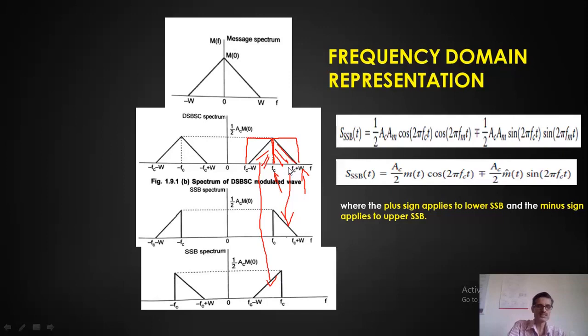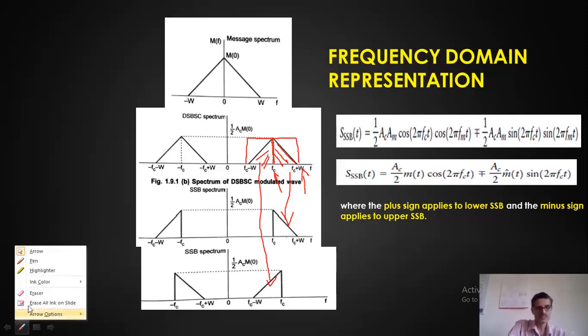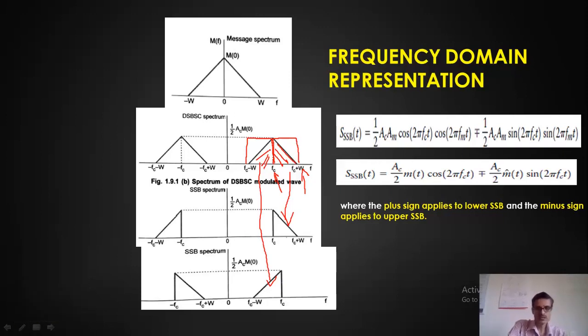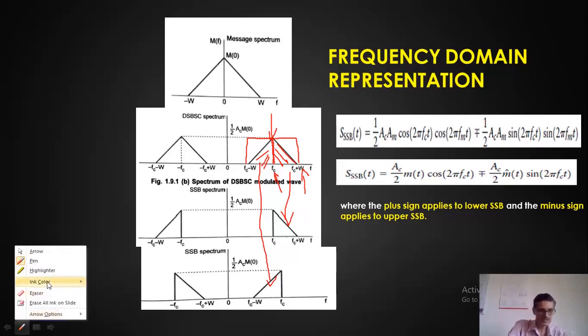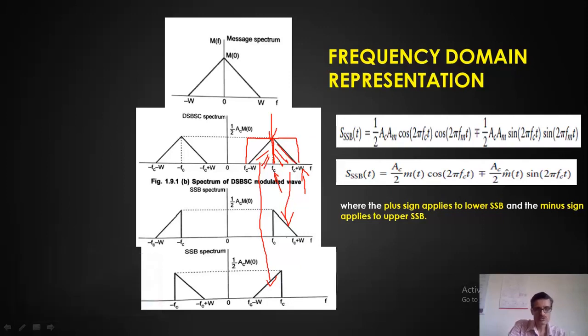Now we will understand the problem, or disadvantage, of this SSB frequency discrimination method. As I told, just look at this. There is no gap between the two spectra, and whatever bandpass filter you design should have a very ideal characteristic. But practical filters will have a response something like this. Let me change the color here to make you understand. So practical filters will usually have a response something like this. This is the response of practical bandpass filters.